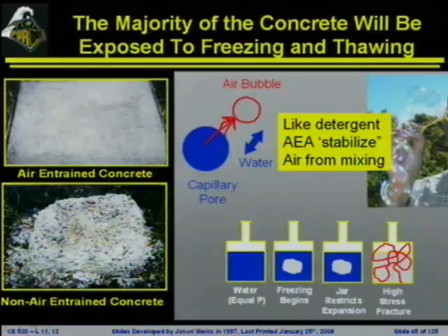Okay. Are these pores generally bigger than the capillary pores? They tend to be smaller, but we'll come back to this and discuss it a little bit more. They'll be around the same size range, and one of the big tricks to making a really, really effective air entrainer is to dictate the size, because most of the time we only want a certain volume of entrained air inside of the system. So if you control the size, in effect you're making it more well distributed throughout the system. You'll hear some people talking about things like micro air and their specific commercial products, which create a very fine porous system across the entire structure, and that's really the holy grail of air entrainment.